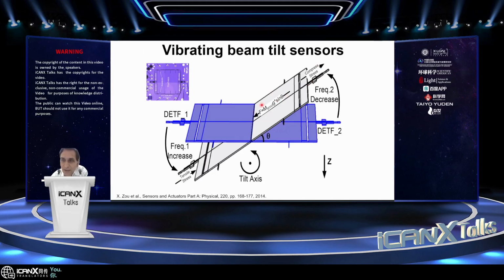And so as you orient the sensitive axis of this sensor at different angles relative to the vertical, the component of the G-force acting on the sensitive axis, of course, changes. That can provide you the basis for a tilt measurement, assuming small g, of course, in this case is a constant.